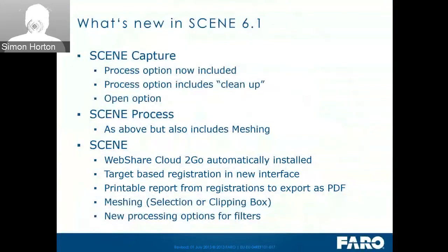So what I'd like to do is run through some of the basic features first off. In Scene Capture, for those that have used it, before it was literally just a solution that would live on a tablet and would allow you to plug the Freestyle in and capture the data. After capturing the data, you would then save that project, move it onto a laptop, and either open it in Scene Process or within full FARO Scene. But what we've now done is given you the option to process that data whilst it's on the tablet.